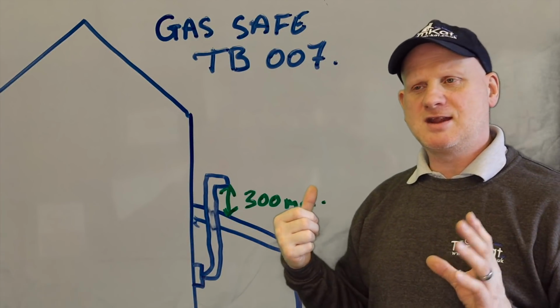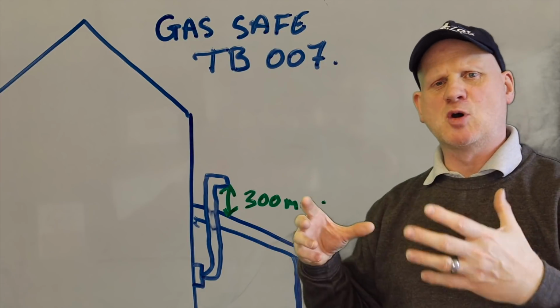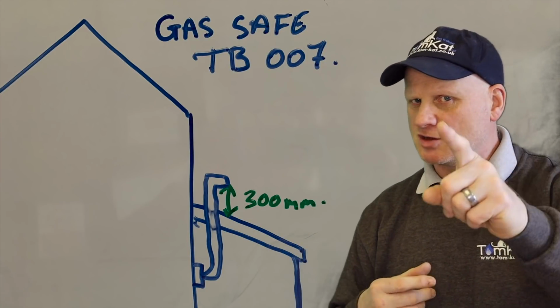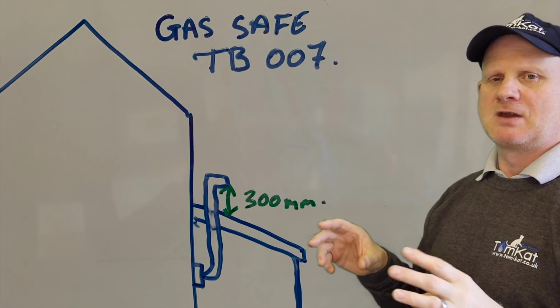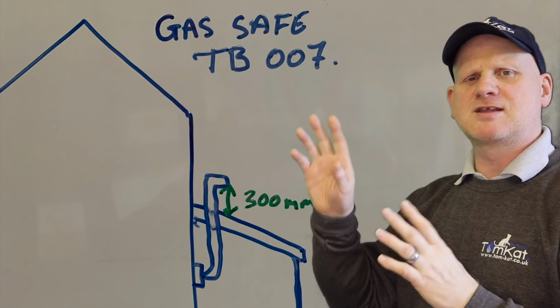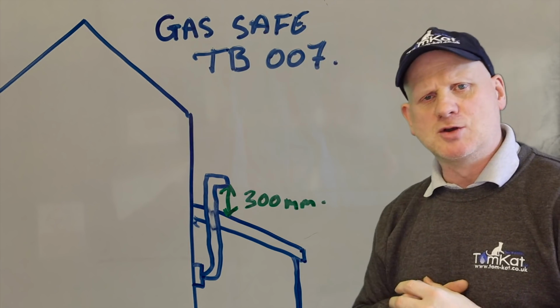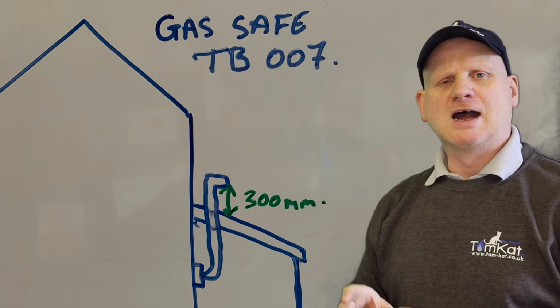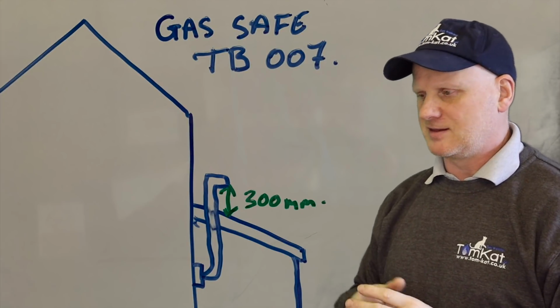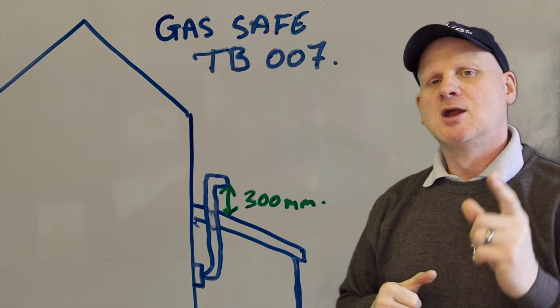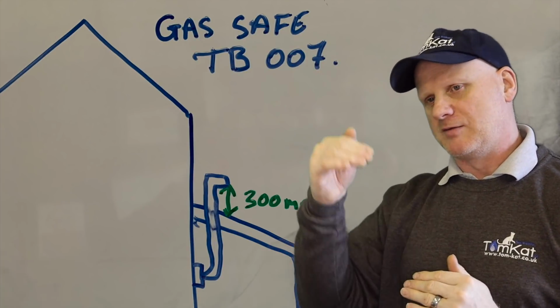So what they're saying is you can, because the carport would be open on at least 2 sides, they say it's got to be open at least 2 sides. They're saying you can stay in the same pressure zone by going up through the roof and terminating facing the same way as the air coming in, but you must be 300mm from the pitch of the roof.